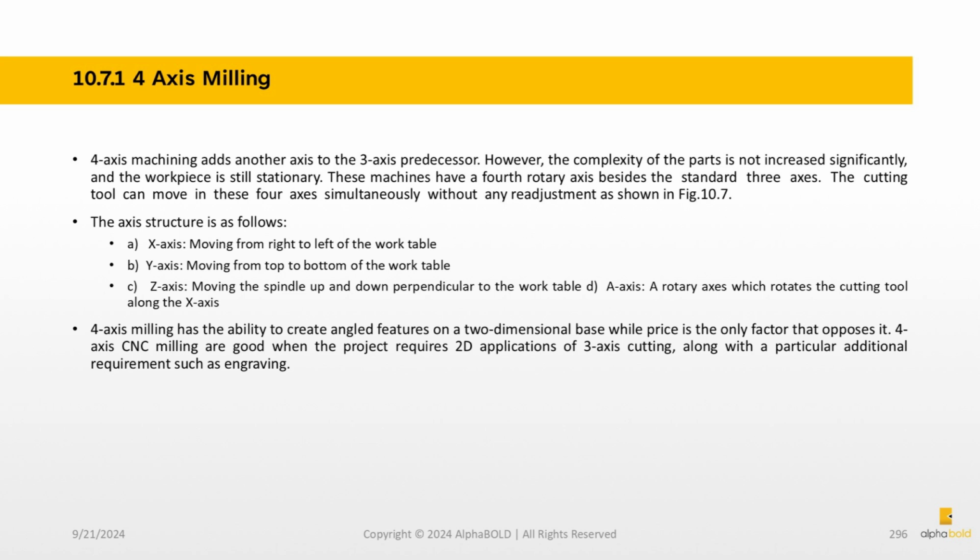4-axis milling has the ability to create angled features on a two-dimensional base, while price is the only factor that opposes it. 4-axis CNC milling are good when the project requires 2D applications of 3-axis cutting, along with a particular additional requirement such as engraving.